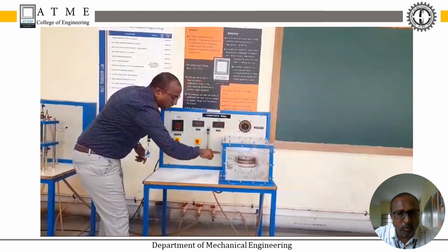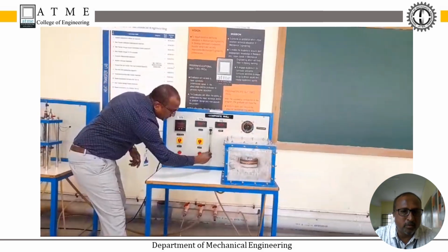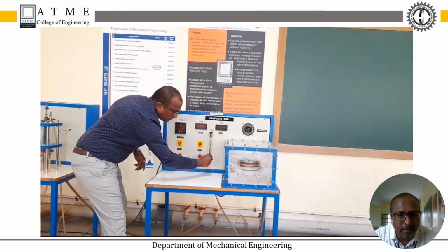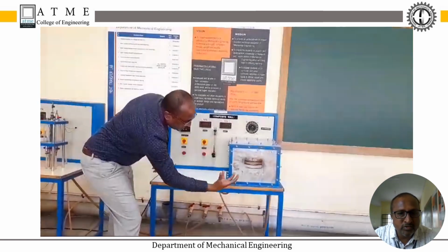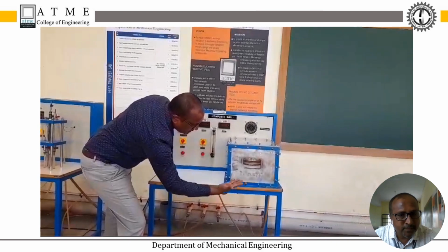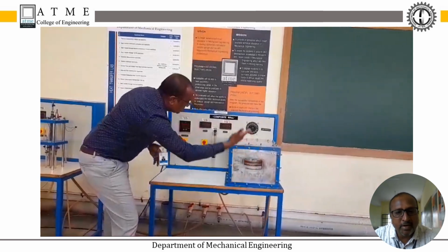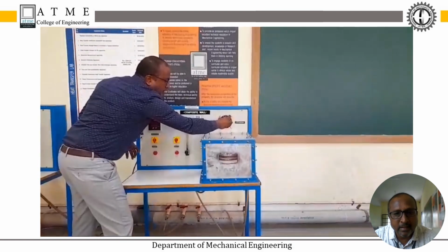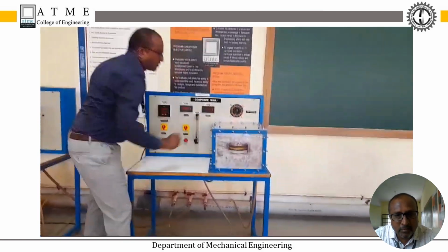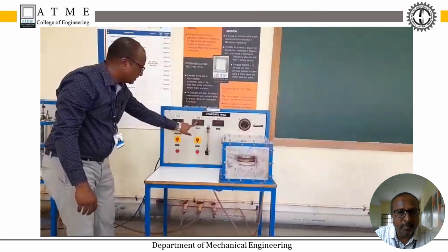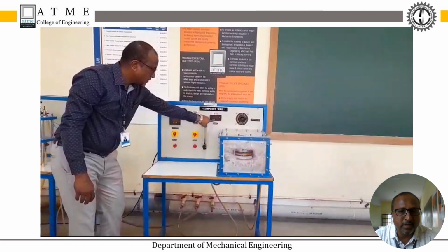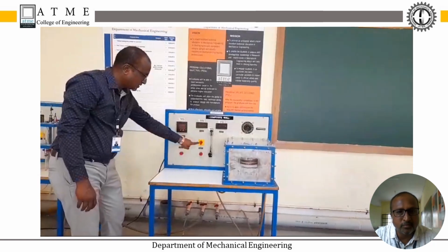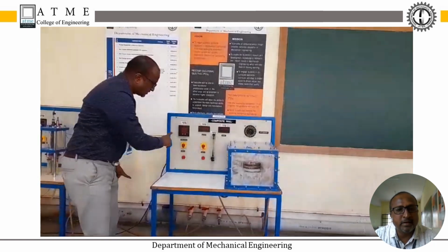The rate of cooling at the top is controlled by the flow rate of water, as I said, and that is controlled using this knob here, which I can adjust as per the requirement. The rate of heating from the bottom can also be controlled using this thermostat, which is turned left or right depending on our requirement to increase or decrease the rate of heating. This panel is going to give us all the readings required. Voltage and current are read there, and this is the place where we need temperatures.